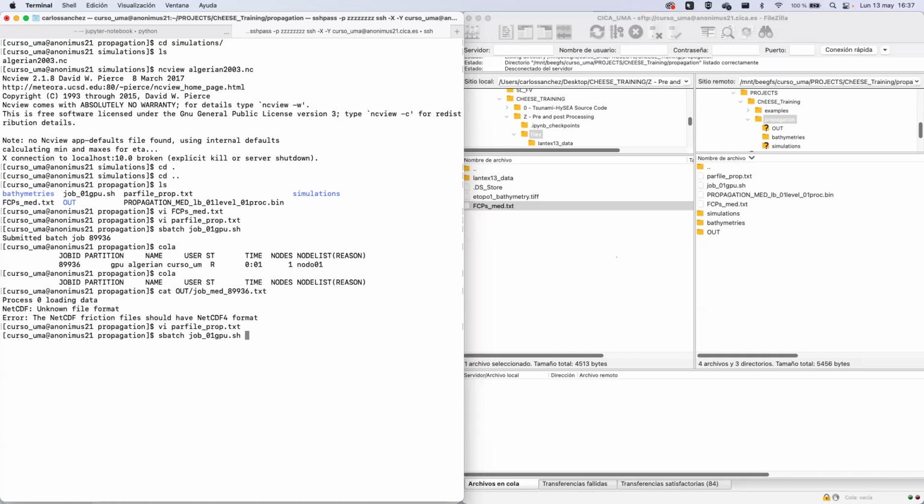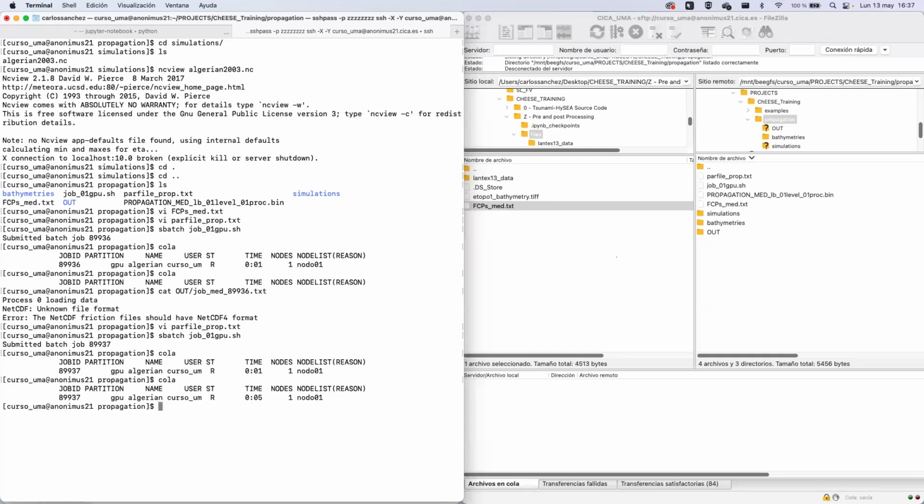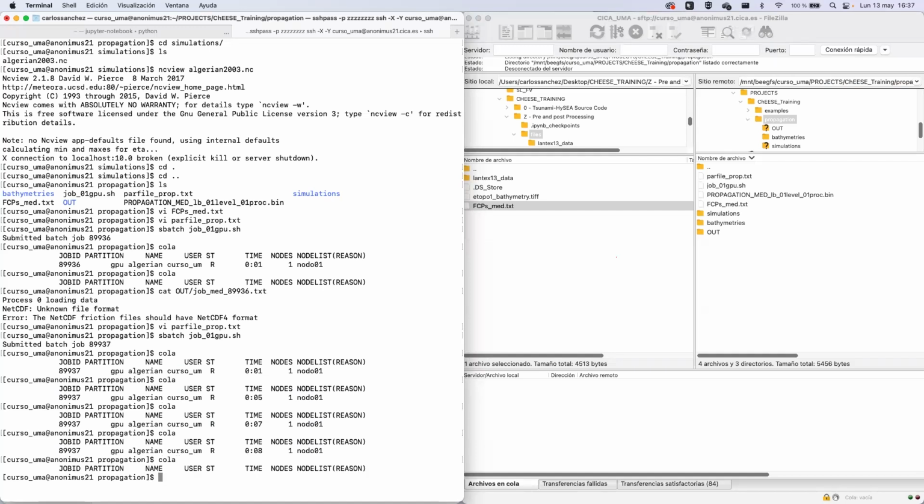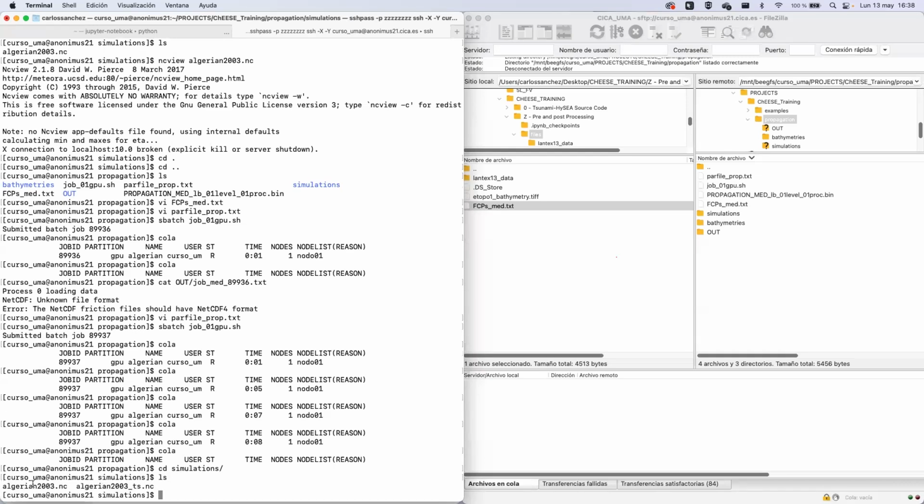Okay, so I run again the bash script in order to run the simulation, and 5 seconds, 7 seconds, 8 seconds, that's just end. And now, if you go to the simulation folder, you will see two netcdf files, one for the simulation and the other one ending in _ts from time series .nc. This file stores the simulation time series for our points.